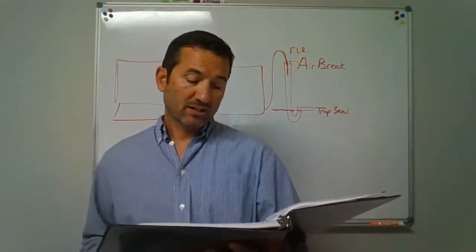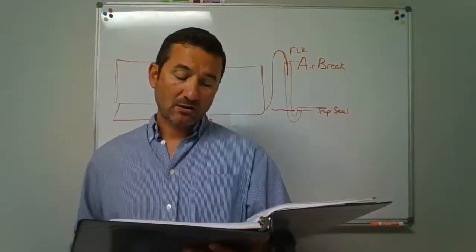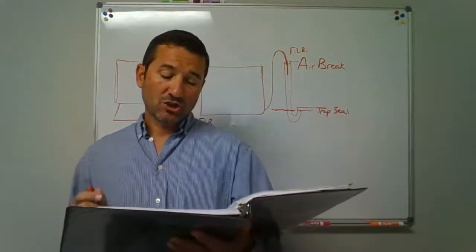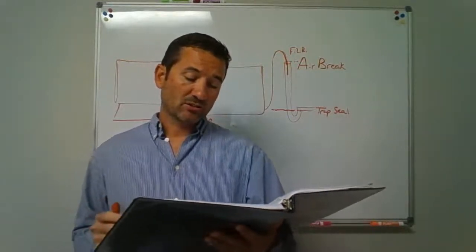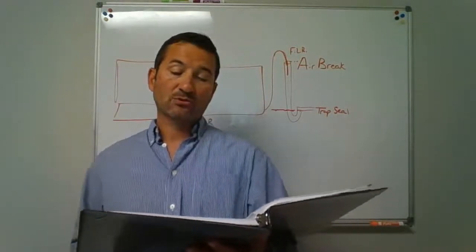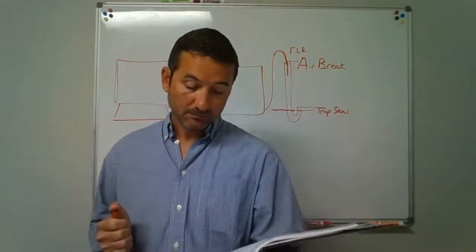Healthcare related fixtures, devices, and equipment shall discharge to the drainage system through an indirect waste pipe by means of an air gap in accordance with 713.3. Fixtures not required by this section to be indirectly connected shall be directly connected to the plumbing system in accordance with Chapter 7, which was the sanitary drainage chapter.